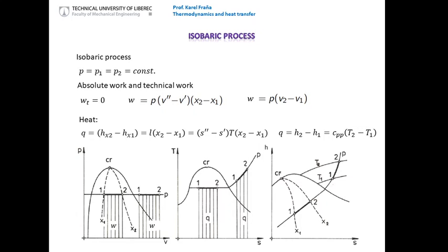Because at the previous presentation, you could see that the enthalpy depends on the temperature and on the c_p, which is the heat capacity at constant pressure for the superheated vapor. And you can use these tricks to calculate, but only for the superheated area, and you should be sure that you are very far from the line of the condensation.